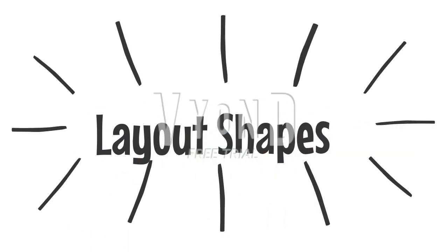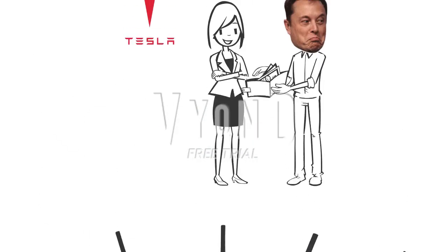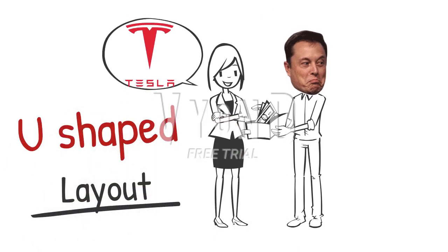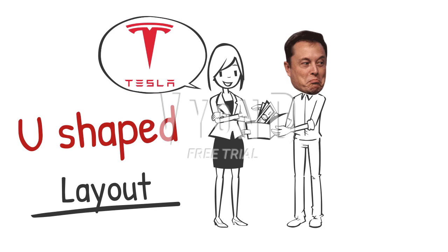Tesla uses a U-shaped layout in its factory which is efficient in space utilization and also gives visibility on the production line. It also makes the input and output sections next to each other, making the design of the receiving and shipping way easier. In a U-shaped line you can even share equipment for different product lines more easily, saving costs on duplicate machines. Hundreds of parts and sub-assemblies are bolted onto and into the vehicles as they move down a linear production line that has been selectively automated to eliminate ergonomically incorrect tasks and the need to lift heavy parts, or simply to speed up the process.